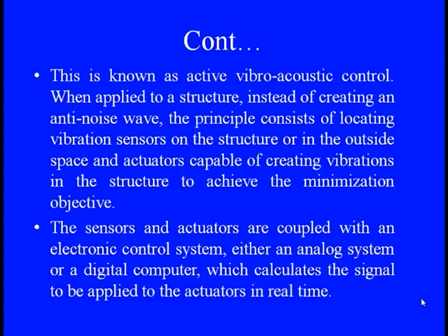Whether we are putting it inside or outside, the sensor is sensing the vibrations, to achieve the minimum objective function, or to reduce in an optimum way the vibration amplitude at the source itself using this vibroacoustic feature. And the sensor and the actuator are coupled in such a way that whatever the sensing signal is coming out is amplified and put into the actuator to generate the required force.